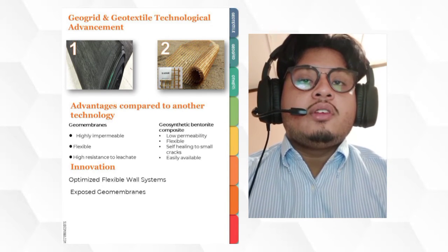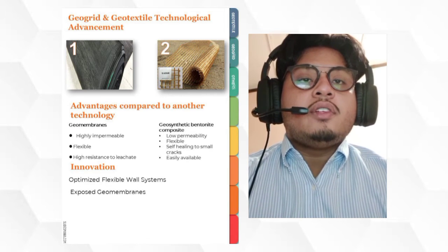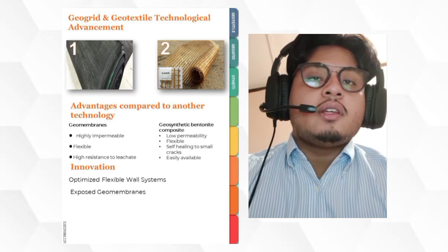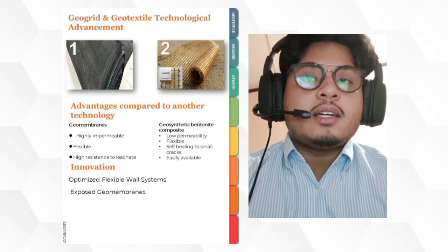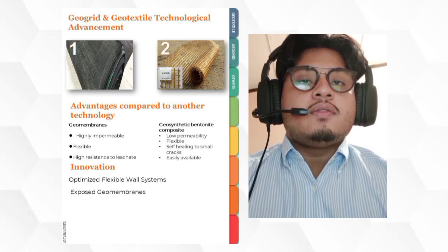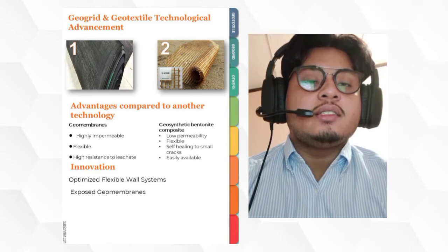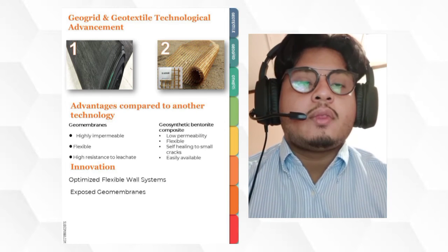Furthermore, these monofilament geotextiles are primarily used to provide filtration underneath materials such as gravel, riprap, large stone blocks, geocell, interlocking blocks, paving bricks, or other types of erosion protection material. They function by restricting soil particles but allowing liquid and gases to easily pass through them.